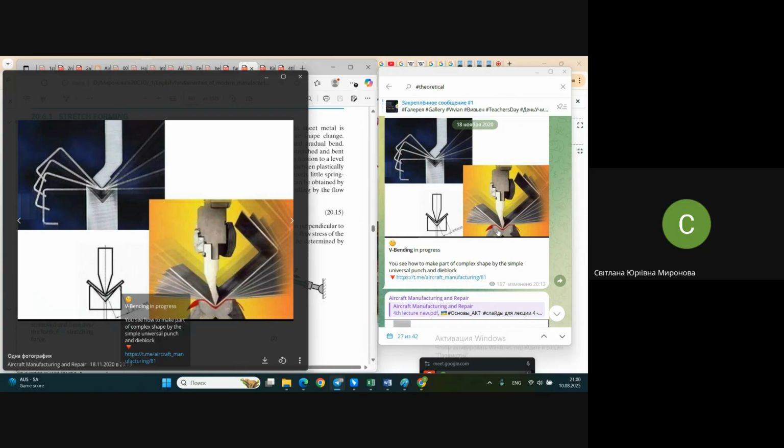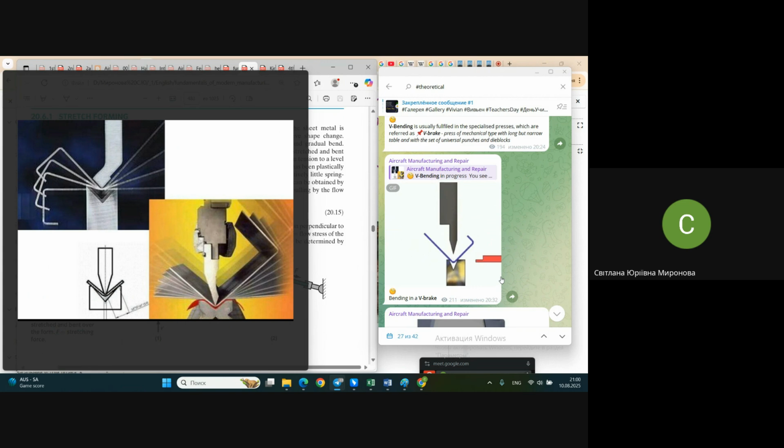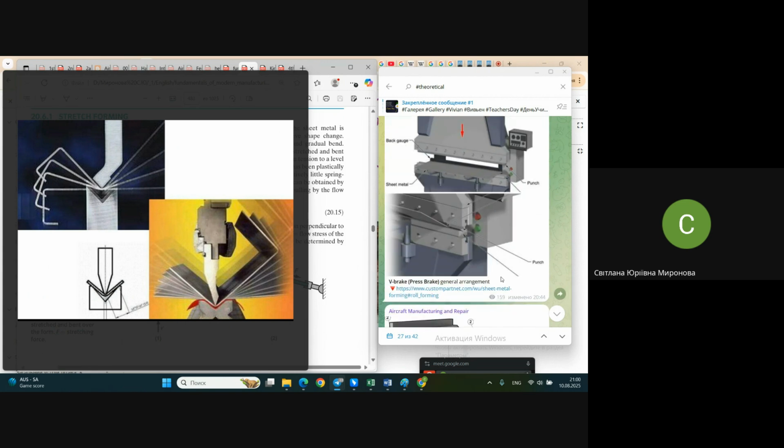Moreover, normally one die block, let me show you in a real photo, not here. No, here it's visible, but not much at the bottom. One rectangular long bar of die block has cuts from 4 sides, at least 4 different cuts. So the same piece of metal is used like 4 different die blocks. It's a quite typical decision. And those V-brake machines are loved by manufacturers,